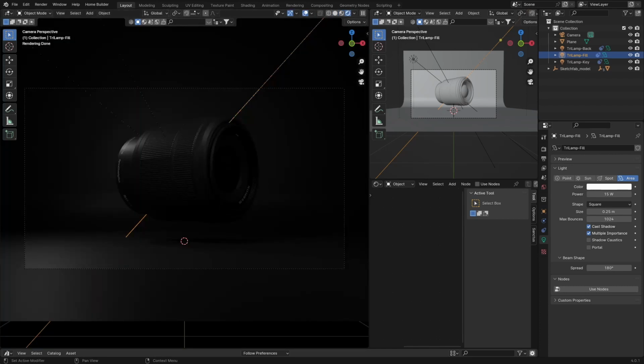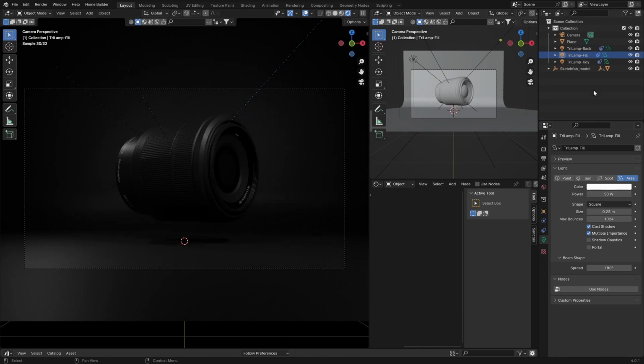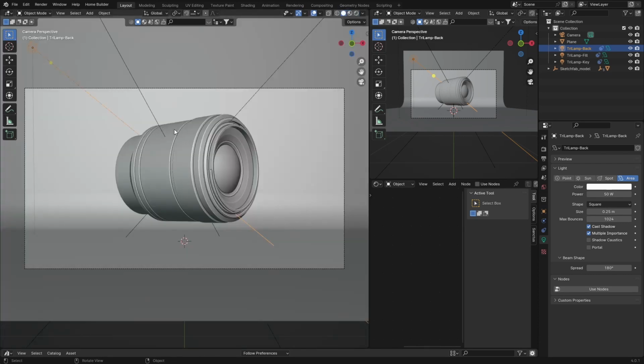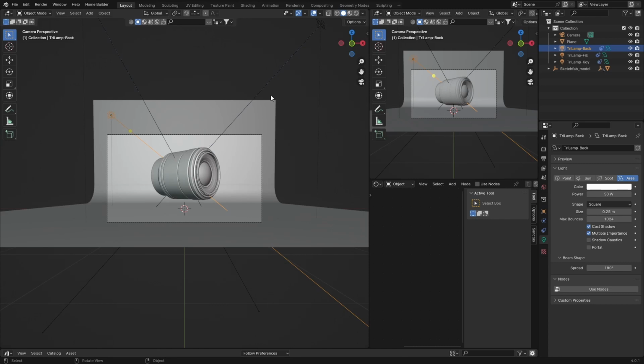Now let's have a look. You can obviously see we need to bring this up, so what you're going to do is, you can see the full light is actually coming from this side, so bring this up to 50, bring this key light to 75, backlight 50. You can see that also looks good. And then you can always add a light, so you can go Shift A to this. This just locks it onto the product, as you can see.